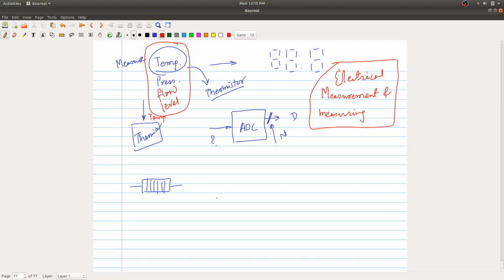So what it explains, the minimum or fundamental circuit, looks like this. I am writing R transducer, that one you have to connect here, with plus and minus terminals going here. This circuit is known as what? Wheatstone bridge, right?